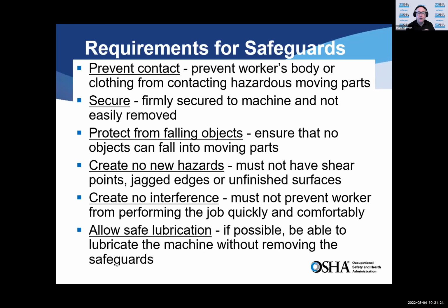So when you secure a guard or safeguard device, it should be on in such a way that someone can't bypass it willingly. It should be accessible, perhaps by maintenance personnel. But again, don't just put a guard on with a zip tie or a wing nut. That's very easily defeated. Put it on with bolts and fasteners, so that it's there and it's working as it should.